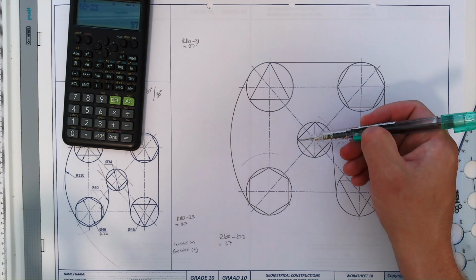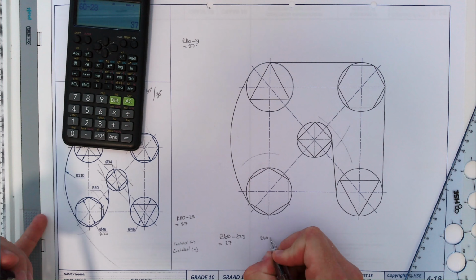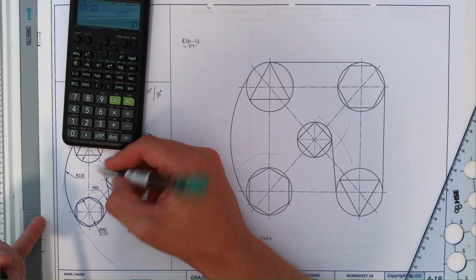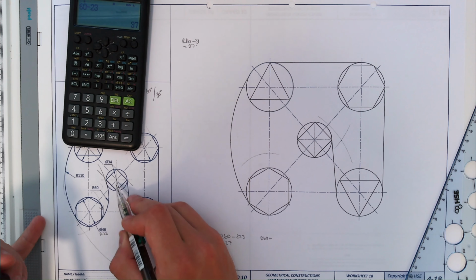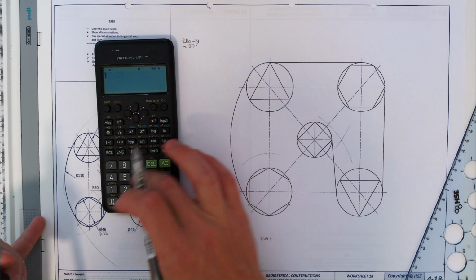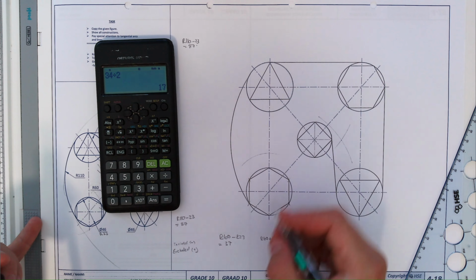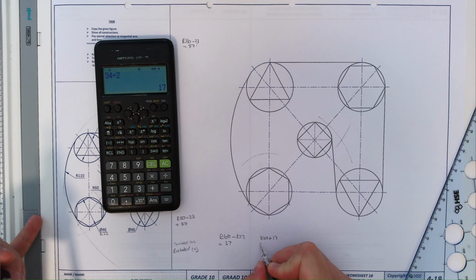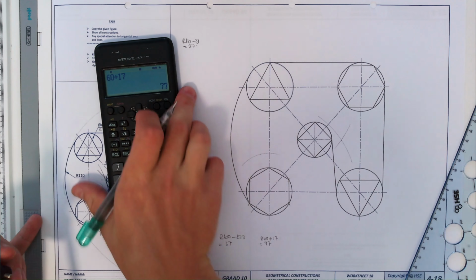Now we're going to do this one's calculation. It is R60 plus, what is this circle's radius? Why this circle? Because the tangent arc is touching that circle. They gave us the diameter of 34. 34 divided by 2 is going to be 17. So 17 added to the 60, we are going to get 77. 60 plus 17 is 77.